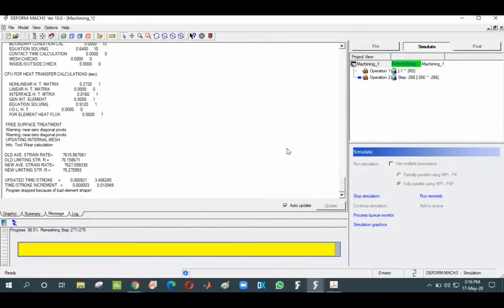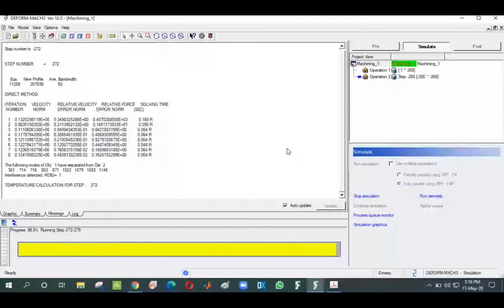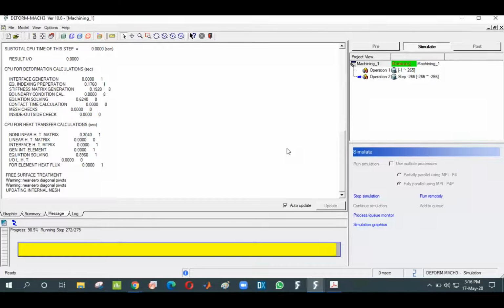Or in the other case, we can use IR thermometers, infrared thermometers, a non-contact type thermometer used for determining these temperatures. Metravib make is there, Fluke make is there. There are many things available for measuring temperatures in non-contact mode, but the precision level will be less than that of the contact type thermocouples.